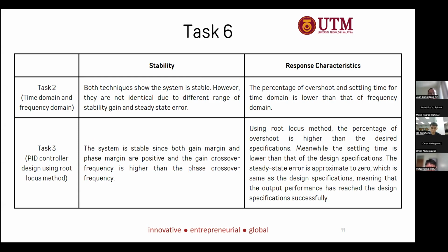So for example, if we want a system with robust stability and performance, then the approach used in task 5, which is lead-lag control design with Bode plot, will be better since it provides comprehensive insight into how the system responds to different frequencies in order to improve stability and performance. If we take another example, if we want a system with quick and simple performance, then the PID controller tuning method, which was used in task 4, will always be effective due to its simplicity and widespread applicability. So that's all.